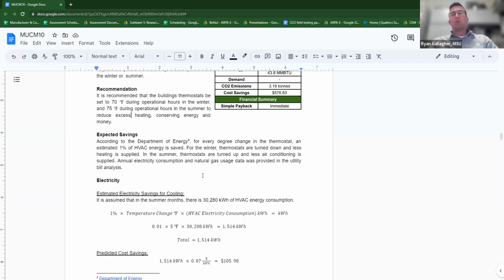But a lot of times we just give control between 70 and 75 and that's it. So that's their range essentially. That's campus standard, that we need to have the buildings at least to 70 in the winter months and at least cool down to 75 in the summer months. And usually that range in between is up to whoever's room it is.